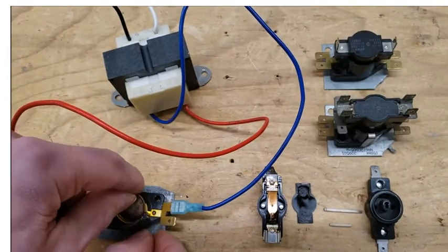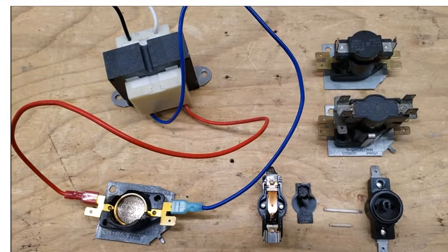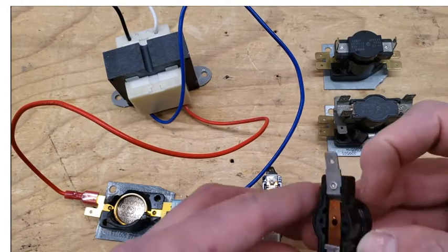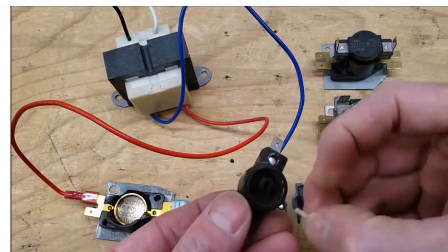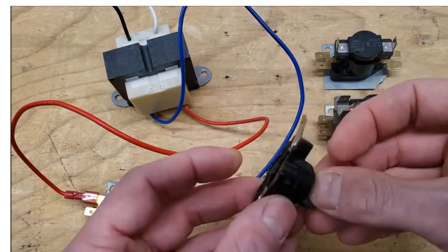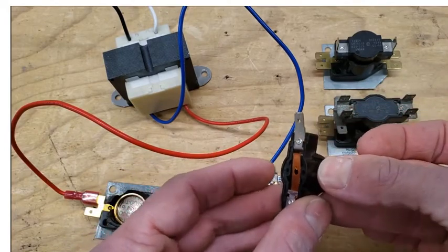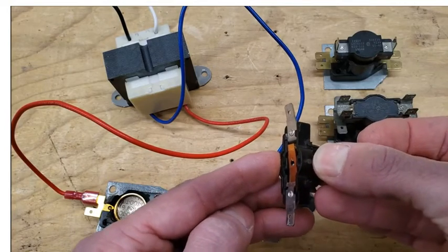So that's what makes up the bottom part, and then this thermodisc pushes up on the rods. So you see these two rods right here? The short rod goes up to the first set of contacts, and the longer rod goes up to the second set of contacts. So in this case right here, this is the first set of contacts. We'll just take the short rod, and normally it's going to be pushing up on this contact just like this, and that's how it's going to be when it's not powered with 24 volts.